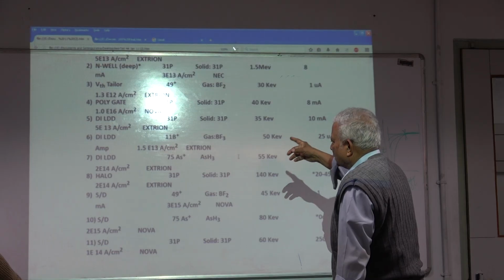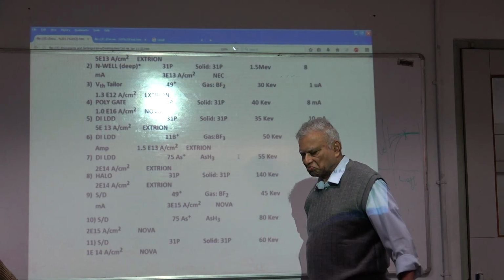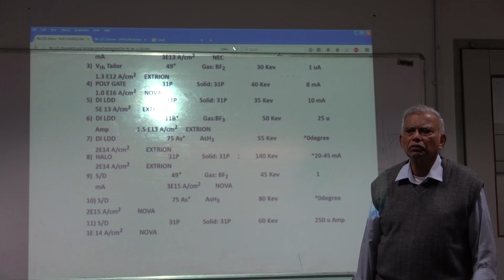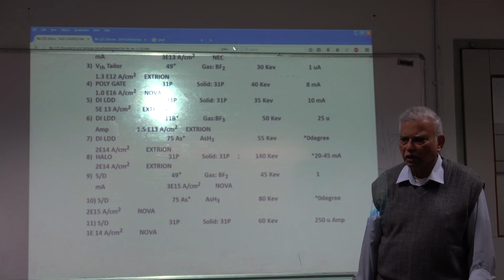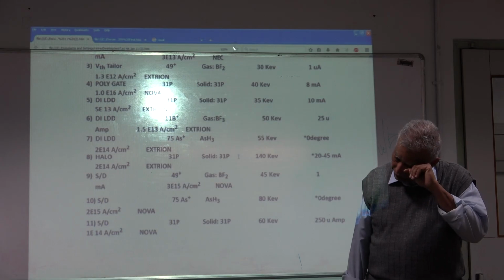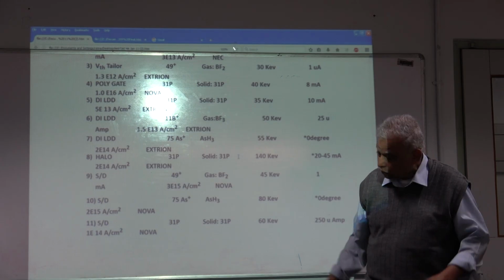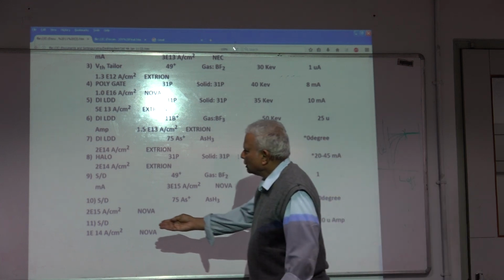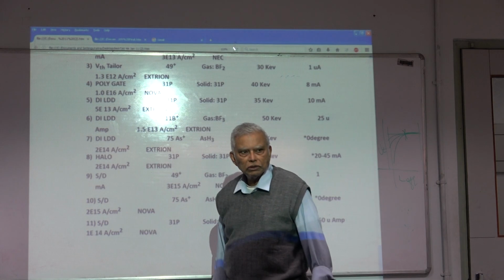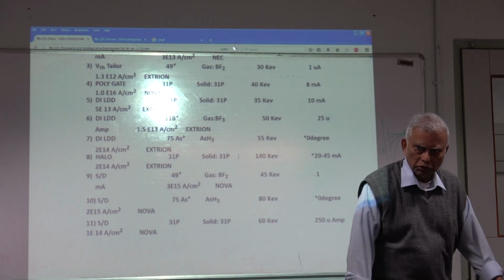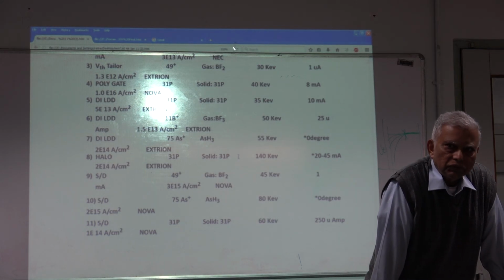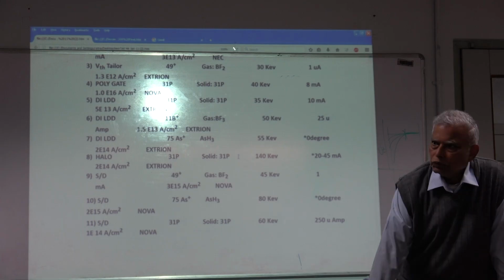To integrate that technology back in 1987, 88, 86, or maybe even earlier, actually in 86, we were manufacturing the high-density devices, where the world has no knowledge how to do this. But back in the early 80s, when we were putting these things together, we're talking about 11 kinds of implants, okay, at different stages. Progressively, as you integrate, 11 implants, 11 diffusions. Take a good close look at those. I leave it with you to figure out why we did this in that order.